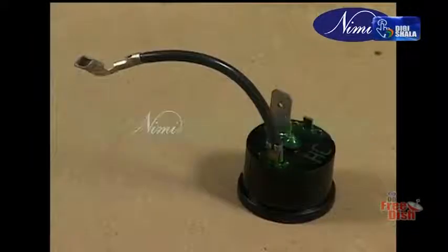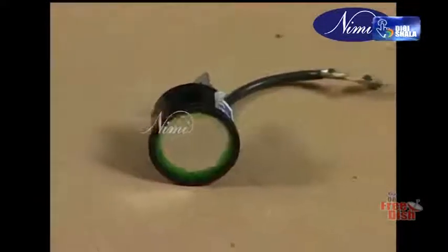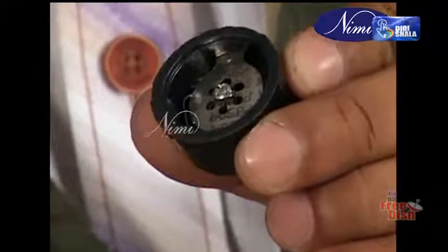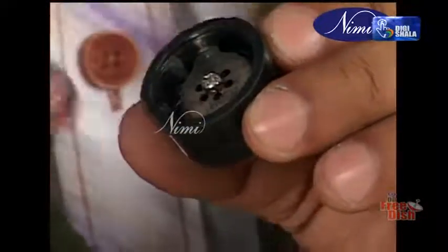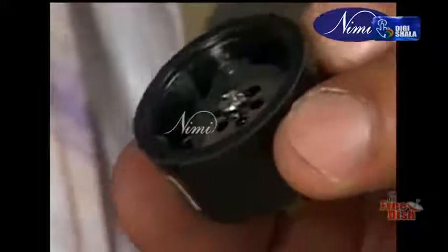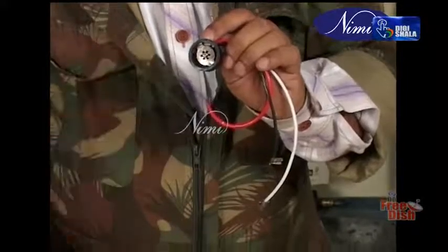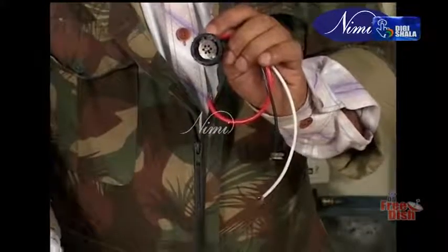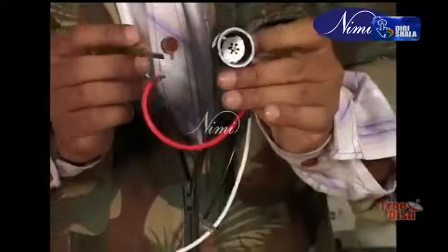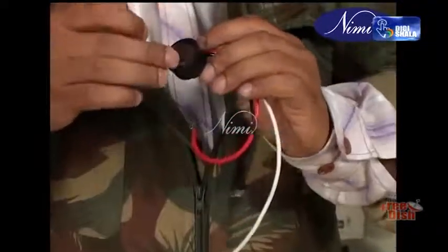Overload protector. An overload protector is connected in series with the electric motor. When the motor draws more current than normal, the OLP stops the motor operation. It consists of a bimetal disc and a resistor through which the current passes, carried by the compressor. When too much current is being drawn, the resistor heats the bimetal and opens the contacts. It will reset in one or two minutes and will try to start the compressor again.